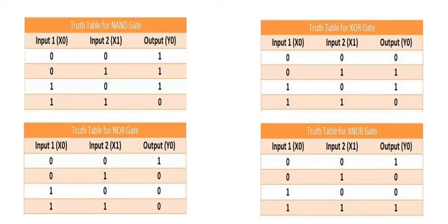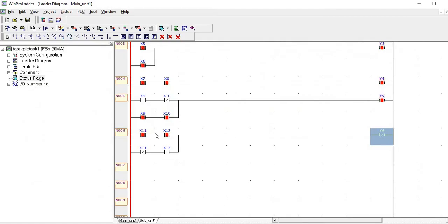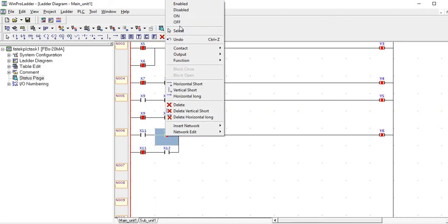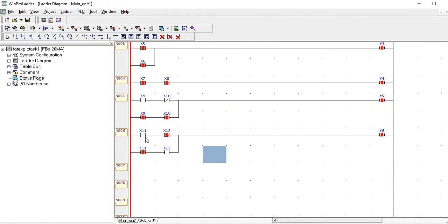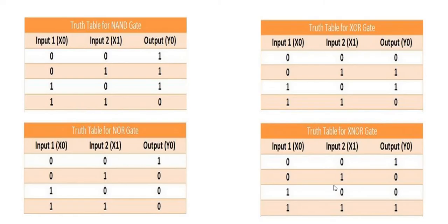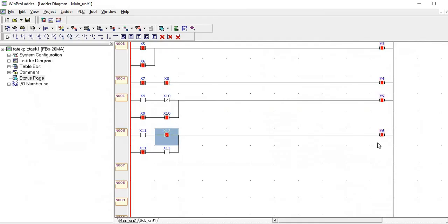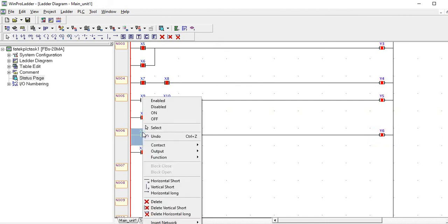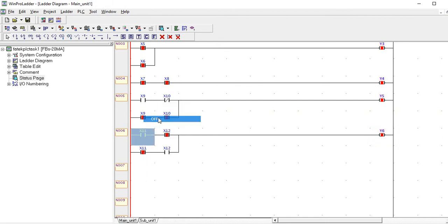Now our output will only be high when both of our inputs are in the same state, meaning when both are high or when both are 0. Otherwise our output will always be 0. Both inputs off, 0 and 0. In the 0, 0 situation our output is high, meaning the LED will glow. When any of the inputs goes high, our output LED will turn off.